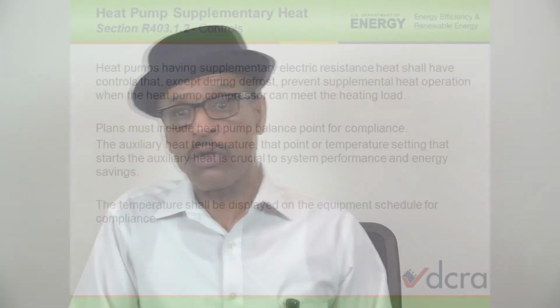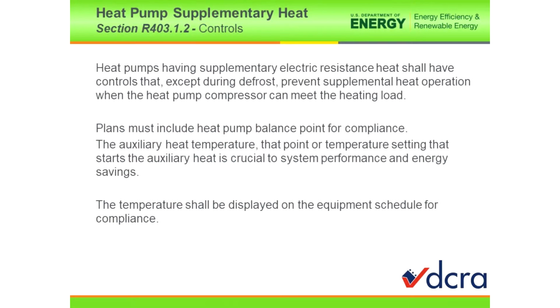So this is why this is a code requirement, so that when the heat pump can still meet the heat demand of the system, then you don't need auxiliary electric heat, okay? But when it can't meet that demand, then that temperature setting, that balance point, needs to be identified in the setup for the thermostat, okay? So we want to make sure that if the inspector goes out there and happens to take a look at this auxiliary heat temperature, then it's set in accordance with what's on these plans, okay? So that's one of the reasons why we want you all to start showing that, okay? It has to do with energy savings and performance, okay?